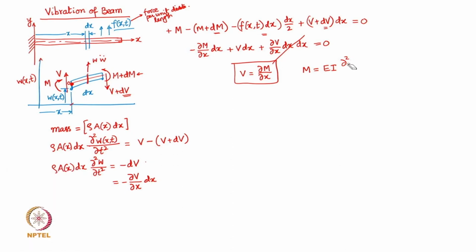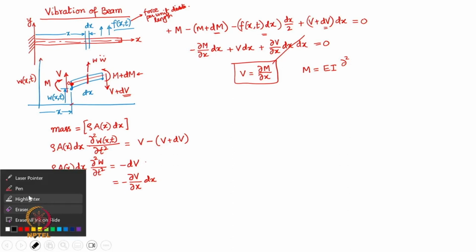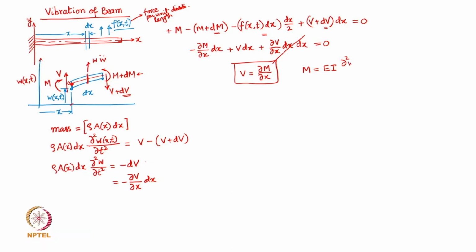Keeping it consistent with the parameter we have here, which is w, this is the well-known relationship that you are aware of. So the bending moment is related to the flexural rigidity EI, and therefore I must again consider the area moment of inertia of the beam about its neutral plane as Ix.